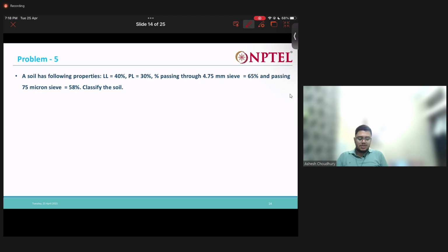So we studied the various percentages between which we need to use dual classification, and above or below those percentages we use other classifications. So 5 to 12%, I guess, dual classification. Below 5% gravel, say, it will be a coarse classification. Above 12% it will be like that. Many things were there. We had studied all those things, right.